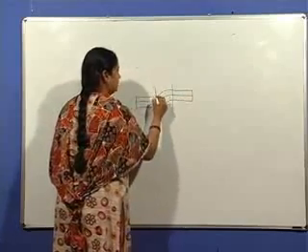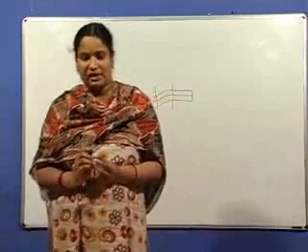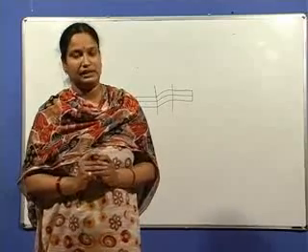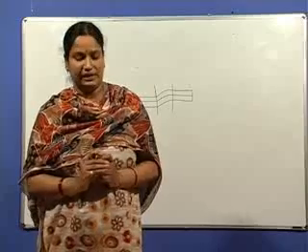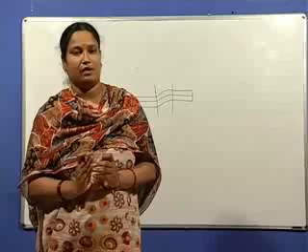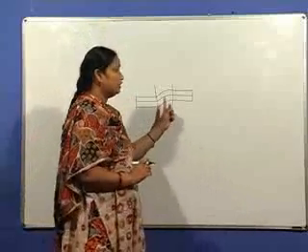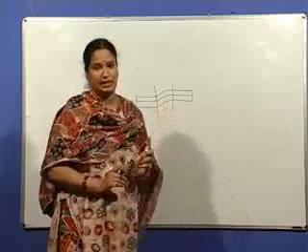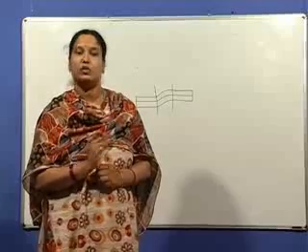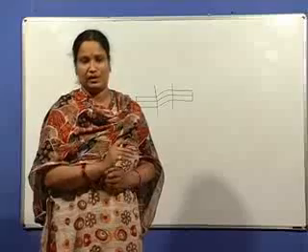So these are known as the kink bands. The metal shears by the formation of dislocation arrays that produce buckling along the slip plane direction, which shears the metal several degrees away from its previous position. The atomic positions do not form a mirror image after shear displacement, unlike in twinning, where a mirror image forms.